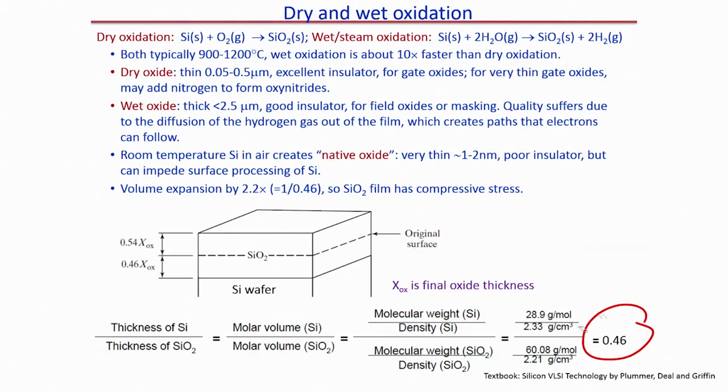So, in the next module we will be learning the techniques to grow silicon dioxide. What have we learned until now? We have learned how to get a silicon wafer from the ingot, and how to create the silicon wafer from polysilicon to silicon. That is one thing we understood. The second thing we understood is that the substrate can be of different types: silicon, glass or plastic. The third thing we understood is how we can grow silicon dioxide on a silicon wafer.